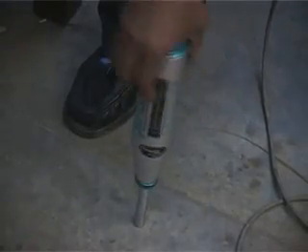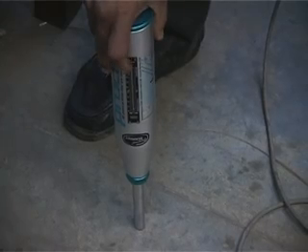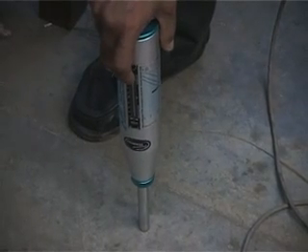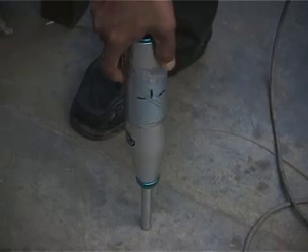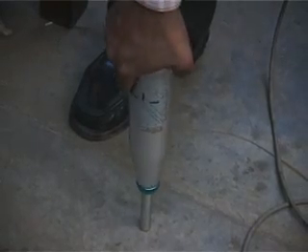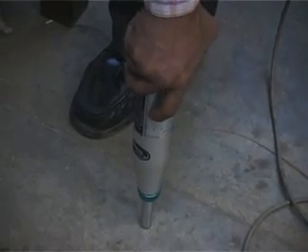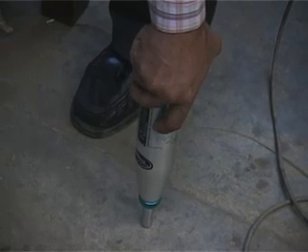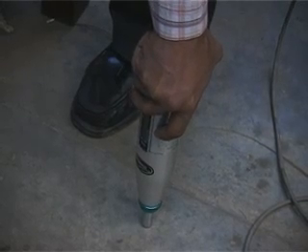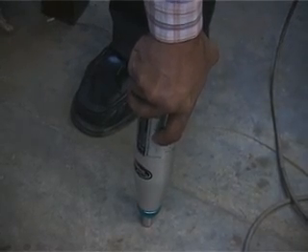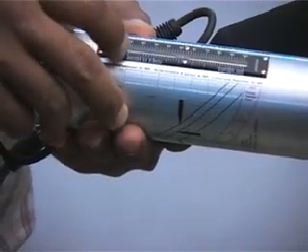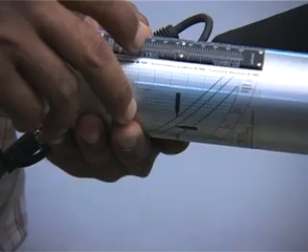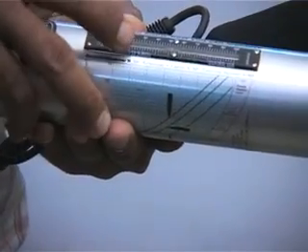We are going to push the instrument in, and we have to make sure that this particular knob is pressed when the rebound occurs, in order to measure the rebound value, and the reading is going to appear on this particular scale here. We did the testing on the floor, so the rebound index is 52.